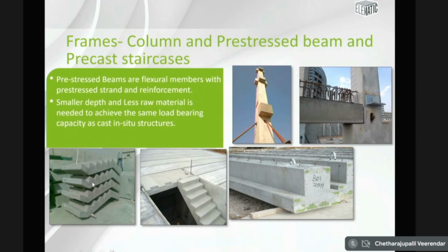And here you can see the precast staircase. Staircases are coming as a single element here, and landing is provided here. So landing has got grooves to receive the staircase, and then it is drilled or fitted together and then again grouted as well.